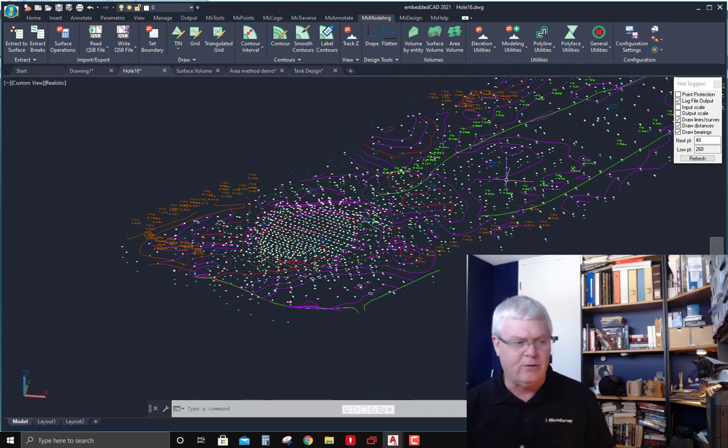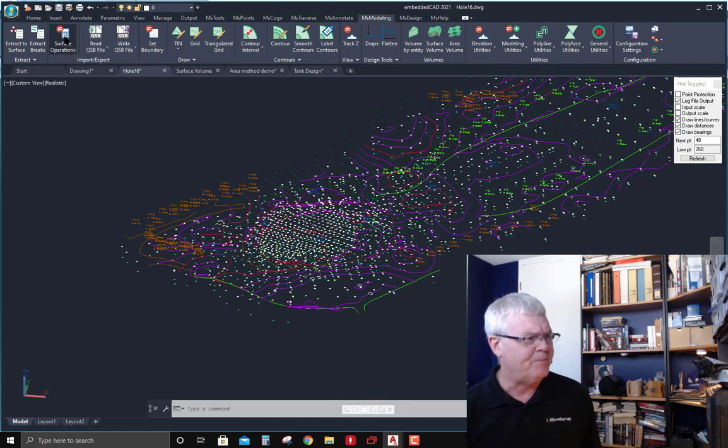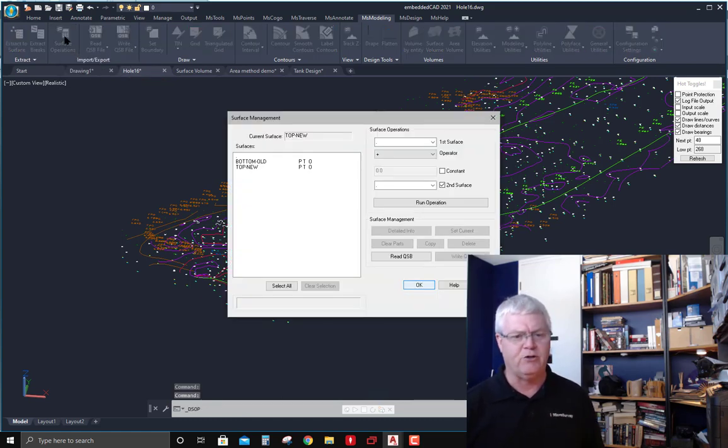It's nice to point out that with Microsurvey CAD, the entities that you need to create a surface are very simple, just 3D polyline, and line, and so forth. Once the surface was created, then a digital terrain model is saved. With Microsurvey, you can plot the surface and represent it using a TIN or using contours or a variety of other options. But the surface itself ultimately is saved as a separate format, a QSB format.